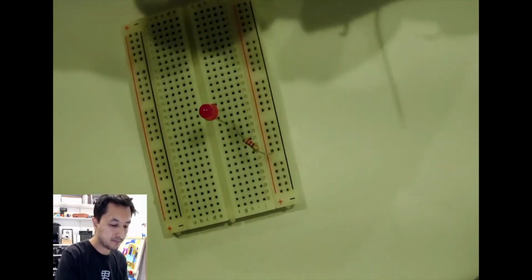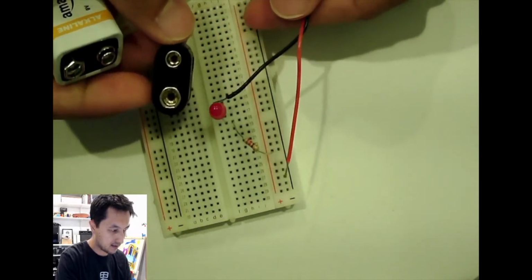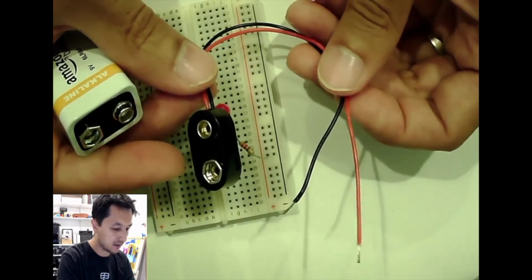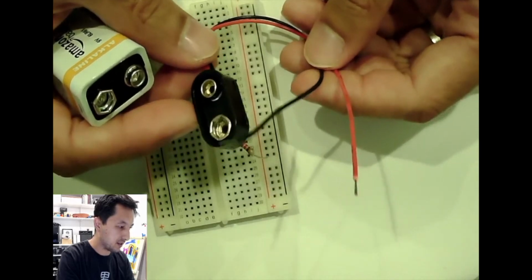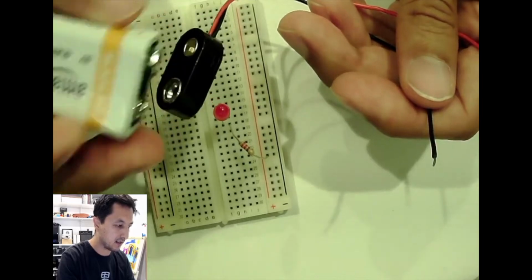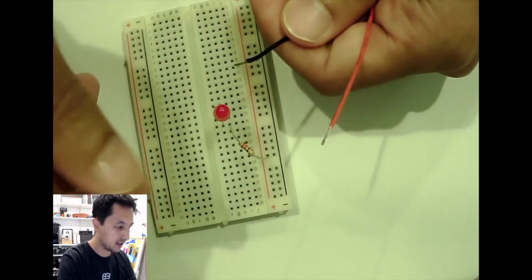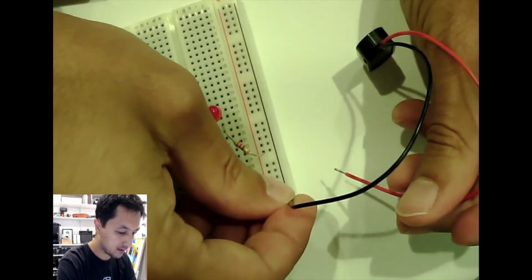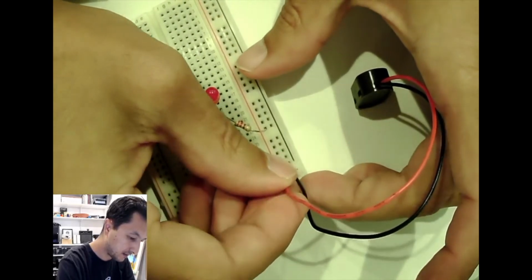And then I'm going to be using this 9-volt battery and this 9-volt battery connector. This might be good for you guys to have too. I don't think it comes in your kit if you're doing anything that's powered by anything other than the Arduino. You might need to get this, but it basically just plugs into the 9-volt battery, and on the other side there are these open little leads that you can plug into the breadboard. So I'm going to plug this one into ground and this one into power.